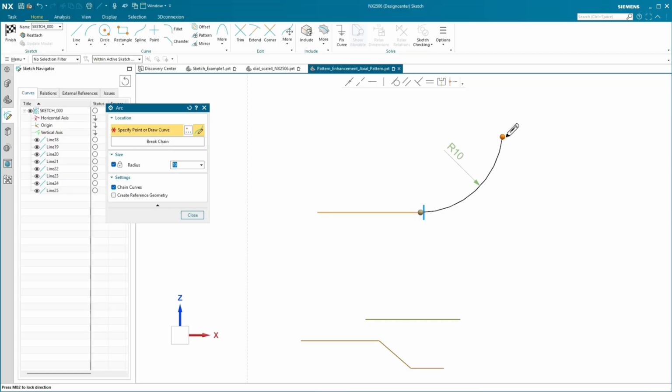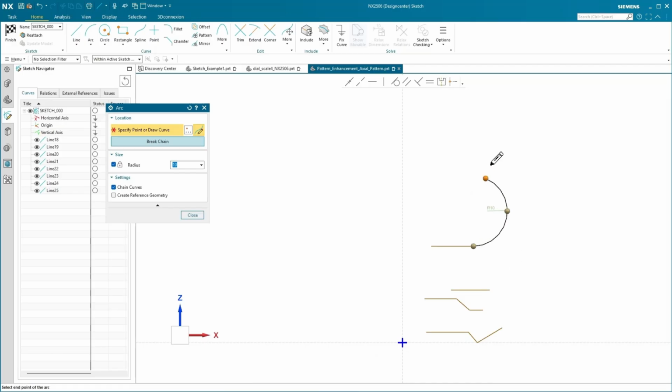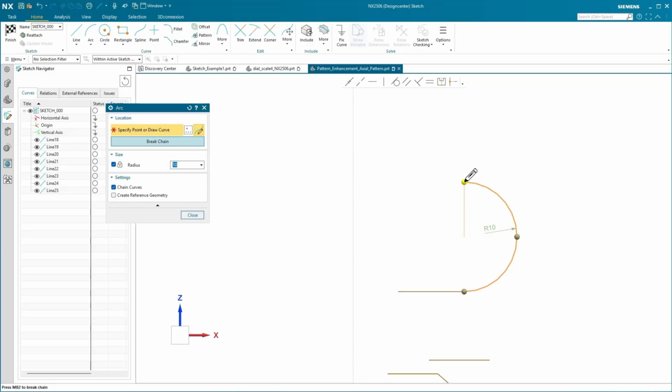All right, snapping locations will also be working here. As you'll note, as I snap to what would be the 90-degree location for the arc, 90-degree angle, if you will, it's going to snap in that location, and then I can left mouse button click and finish the arc. All right, now that I've created that arc or clicked in, I can go ahead and finish the rest of the arc and come around and finally click on the final location, which would be the 180-degree angle snapping location here, and finish the arc.